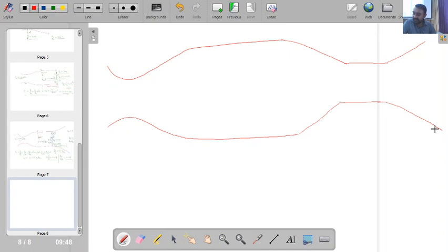Okay, here what will be happening? At this point I need exit Mach number ME, pressure will be PE, here pressure will be P naught. Then here pressure will be once again 1 atmospheric, P infinity. Okay, now I have two throats, one is this, one is this.